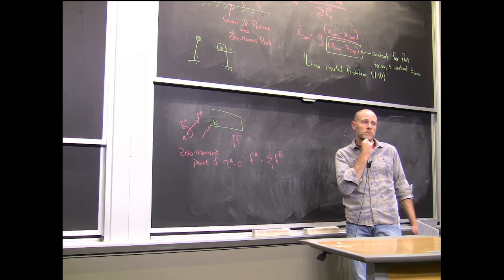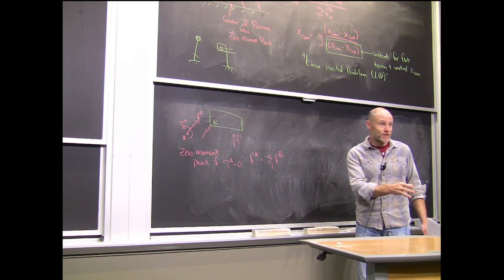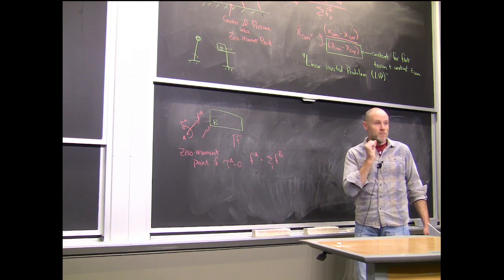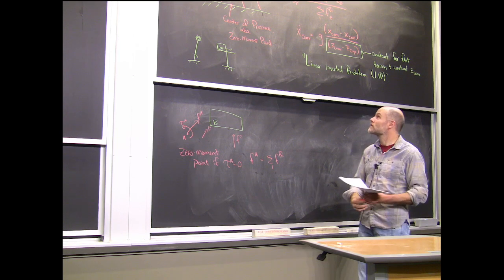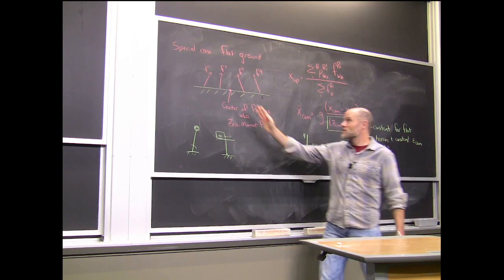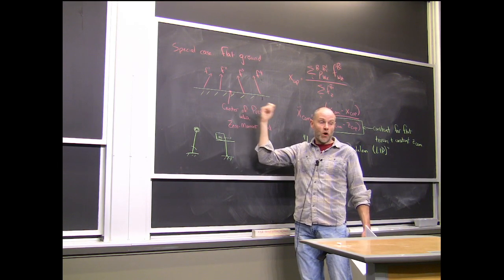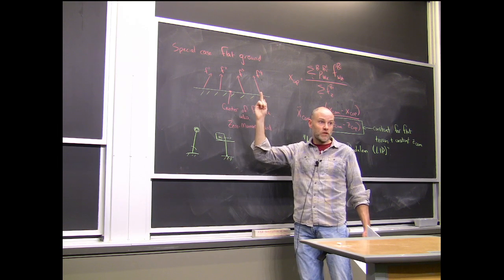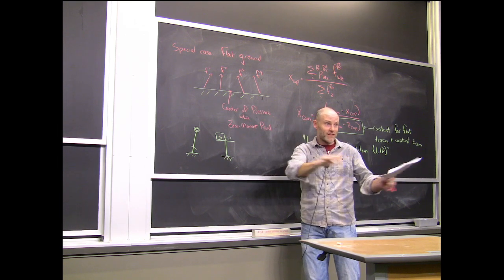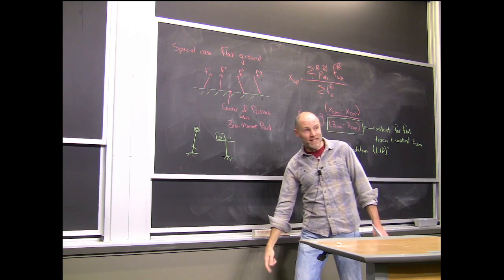What would be the motivation of setting up this whole concept of zero moment points? Is it more computationally efficient? It's partly the answer to Frank's question. The question is, what's the motivation? Part of the answer is that I don't have to do any detailed modeling of the ground reaction forces. If all I know is where the zero moment point is on the ground, then I already know what my center of mass is going to be doing. So it actually obfuscates the complexity of the ground reaction forces. It also happens to be an easy thing to measure.